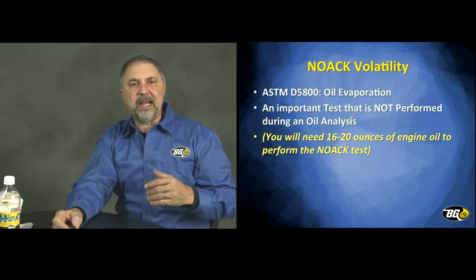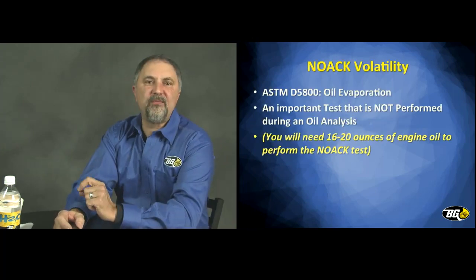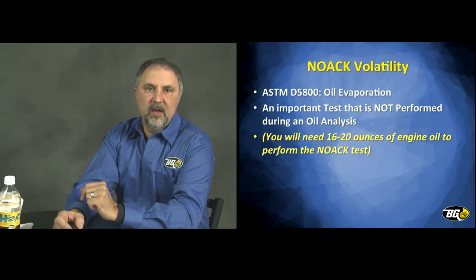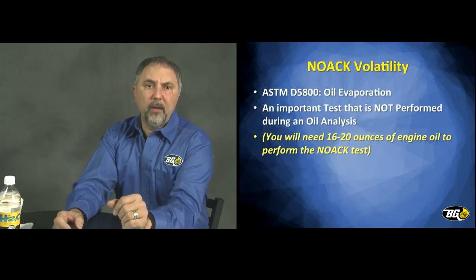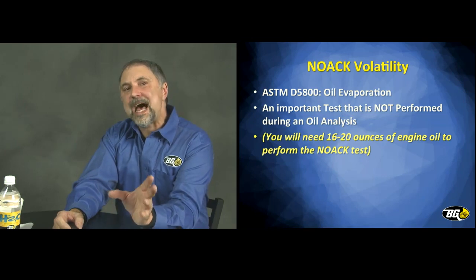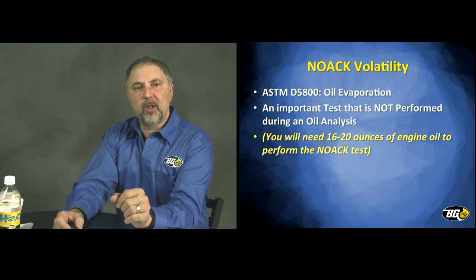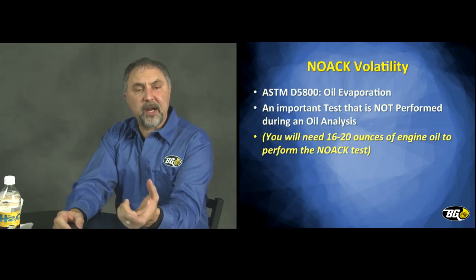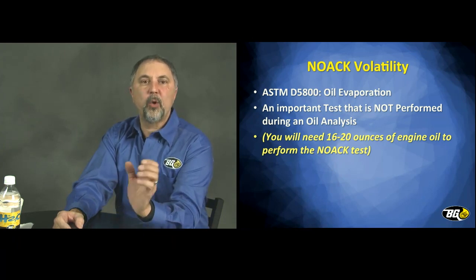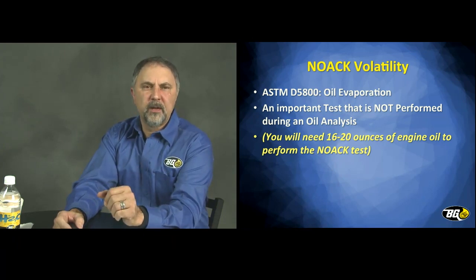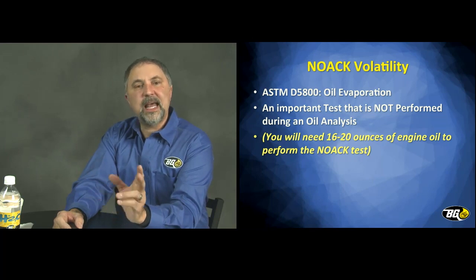There's an important test which you're probably familiar with from the GDI if you've been around for a little bit. In our GDI classes, we talk about that NOACK volatility test. This is something we have a competitive advantage on. Oil is not oil. And this is a test that's not normally performed during an oil analysis. You have to request this. In that oil sample bottle that I showed earlier, not enough. You need at least 16 to 20 ounces of oil in order to have this test performed. It's called a NOACK volatility, and it's an ASTM test.